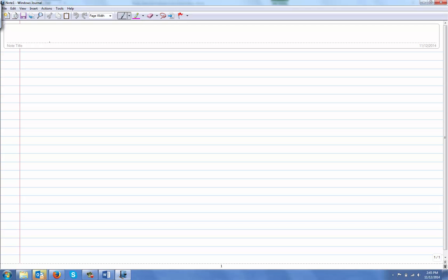I think you can get away with half-inch. Half-inch plywood's fine. Over that, is that not plywood, the fiberboard or whatever, OSB? Yeah, whatever. No, I would use plywood. That's just gonna swell up on you after a while. OSB is full of glue and when it gets wet it starts... Or really hot. Or really hot, yeah. It could fall apart on you.